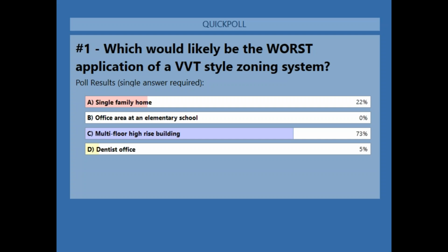An air handler, 90% of the time, is going to be physically inside the enclosure of the building, in the attic space, above the ceiling cavity, in a mechanical room, something like that. However, sometimes an air handler gets put on the roof. Well, then why isn't it called a rooftop unit? I don't know. The manufacturer has it in their catalog as an air handler. It's normally an indoor thing, and you've asked them to build it to be outdoor rated, and they do that for you, and they still call it an air handler.